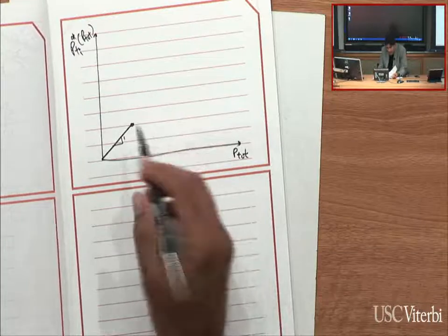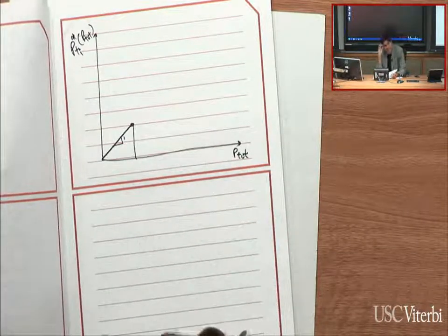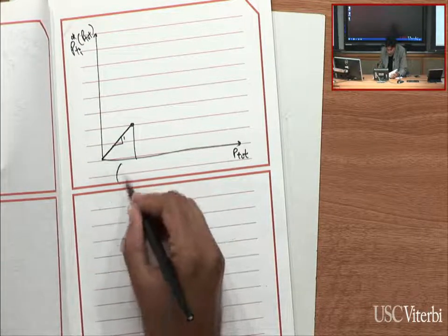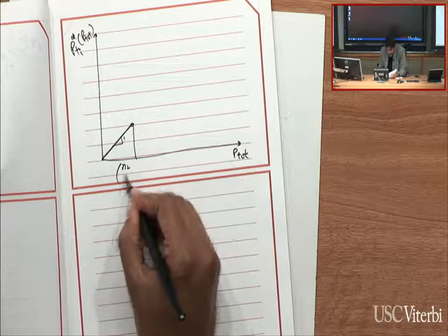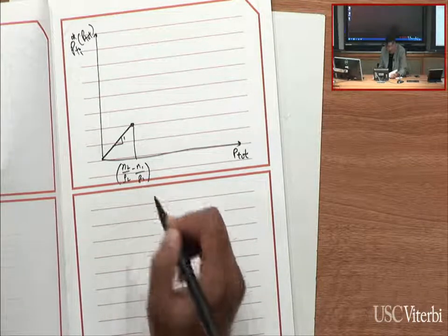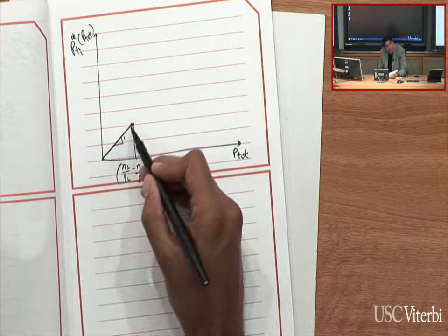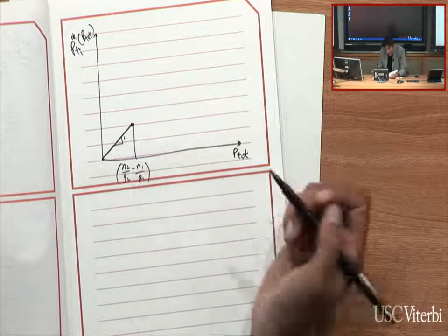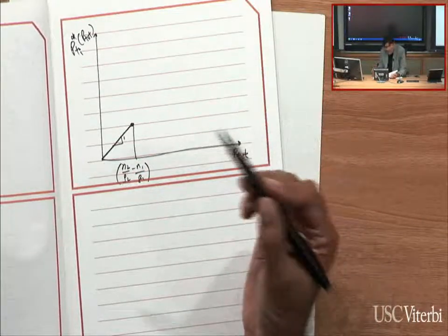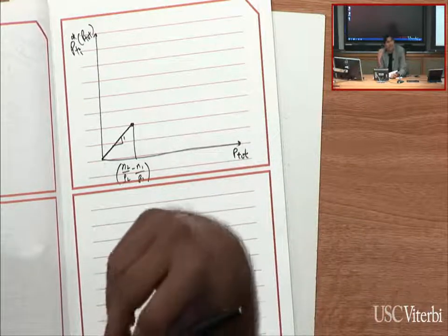Up to what point? Well, it's up to the point where P total equals the gap between how good the first channel is and how good the second channel is. Right? So it's up to that point, N2 over G2 minus N1 over G1. So long as my total power is less than that number, we put it all in channel 1. At this point, channel 2 starts to get some power. And channel 1 continues to receive power. And they both get the same amount of power.